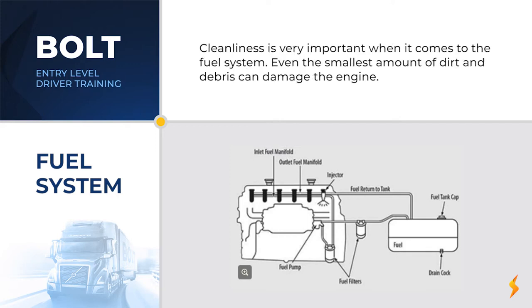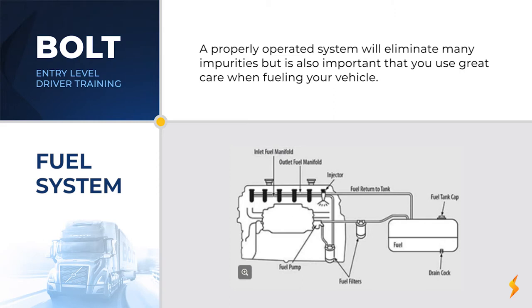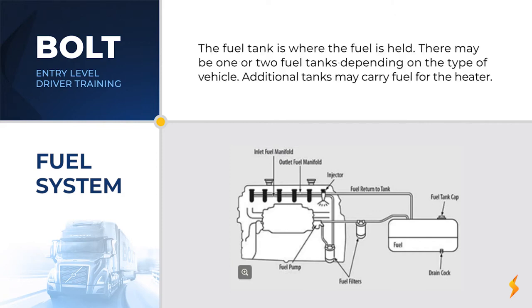Cleanliness is very important when it comes to the fuel system. Even the smallest amount of dirt or debris can damage the engine. A properly operating fuel system will eliminate many impurities, but it is also important that you use great care when fueling your vehicle. The fuel tank is where the fuel is held.